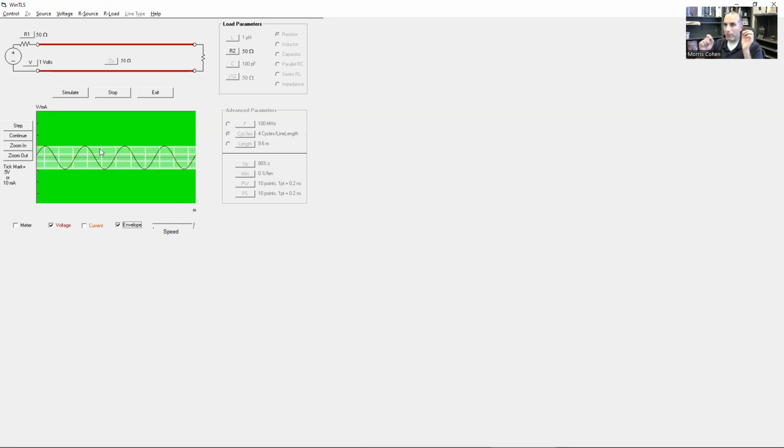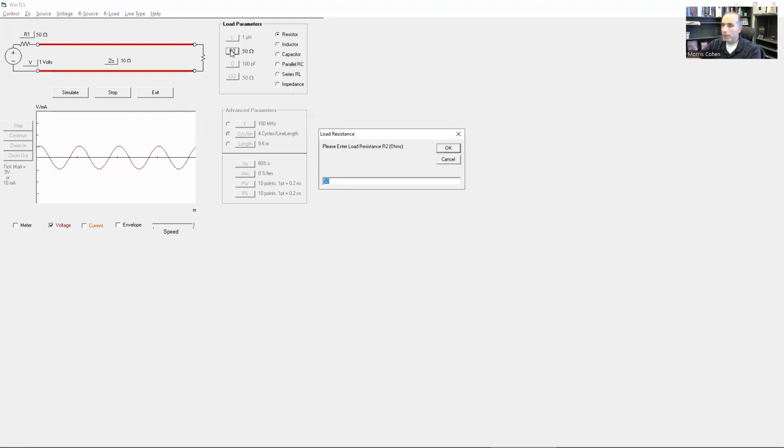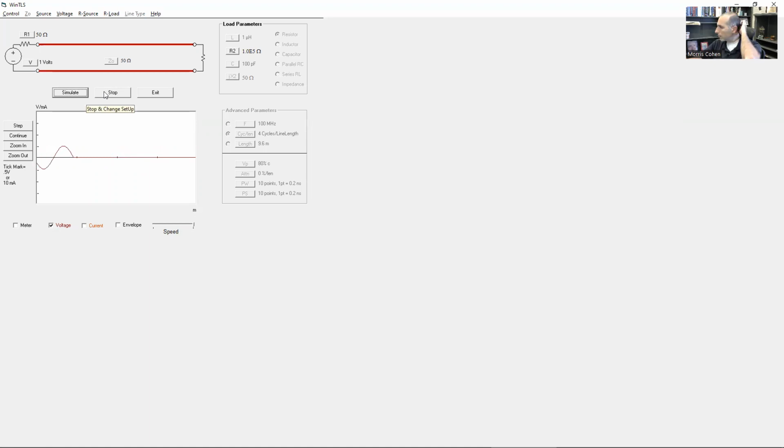However, if you have an oscilloscope and you place it in 2 different locations, the sinusoid that you see will have different phases with respect to each other. And that's because this is a moving wave, as opposed to 2 crisscrossing waves that effectively cancel each other out. So this is a purely propagating wave, whereas the case of a really big, effectively open circuit is a standing wave.